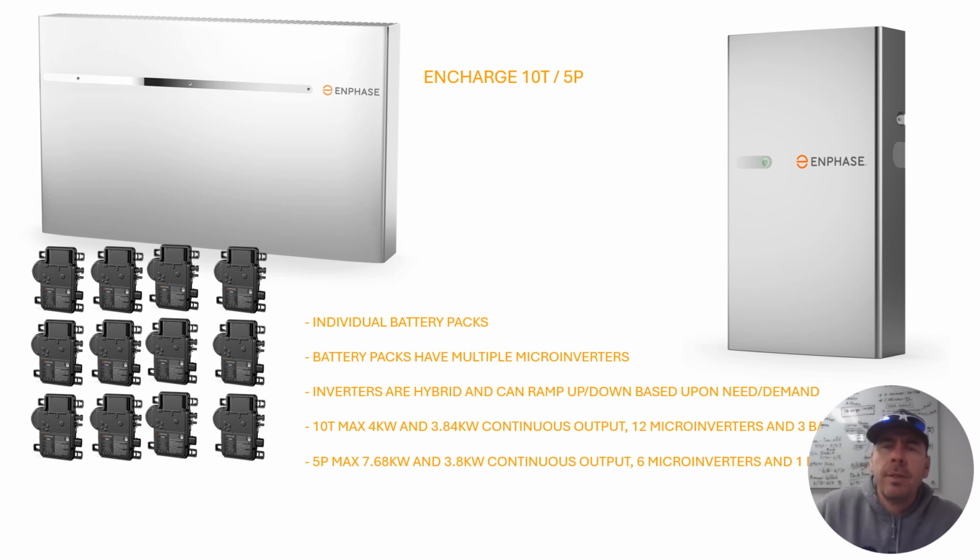This is the battery component. There's the 10Ts, which are now being phased out, and the 5Ps are taking their place. Inside the 10Ts or 5Ps are individual battery packs, and each of the individual battery packs is tied to multiple inverters. Inside the 10T, there should be 12 microinverters and 3 different batteries, so that's 4 microinverters per battery. The 5P has 1 battery and 6 microinverters attached to the 1 battery.